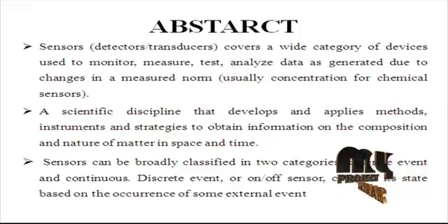For vapor detection, a highly sensitive miniaturized resonant sensor is of greatest interest for many applications, including consumer, industry and environmental applications. An operational amplifier based multi-channel oscillator that interfaces with a 50 MHz capacitive micromachined ultrasonic transducer array is presented for chemical sensing applications.